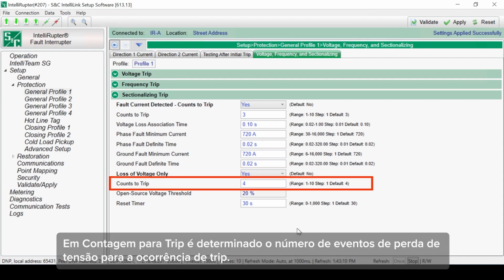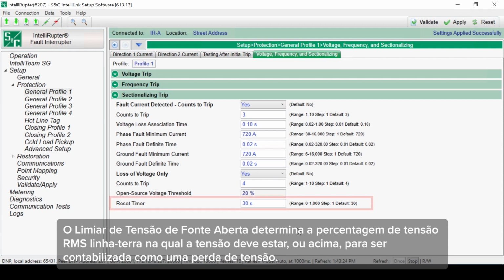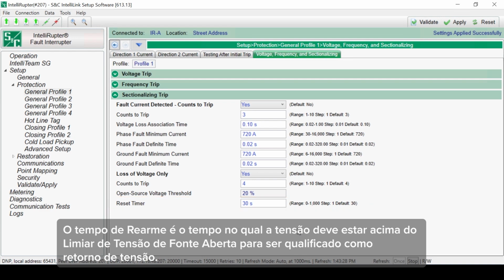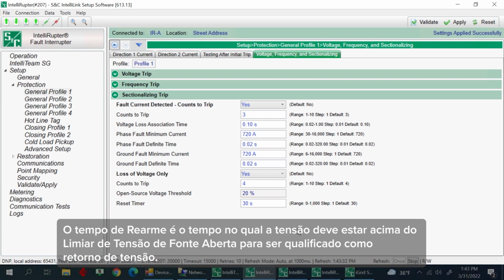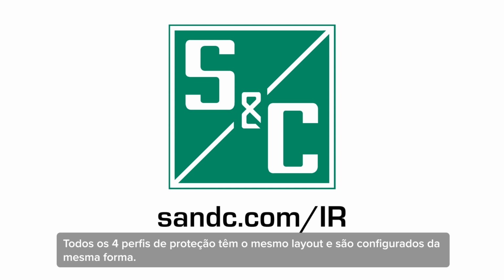Counts to trip determines the number of voltage loss events for tripping. The open source voltage threshold determines the percentage of line-to-ground RMS voltage the voltage must be at or below to be counted as a voltage loss. The reset time is the time the voltage must be above the open source voltage threshold to be qualified as a return of voltage. This concludes configuration of the general protection profile. All four protection profiles have the same layout and are configured in the same way.